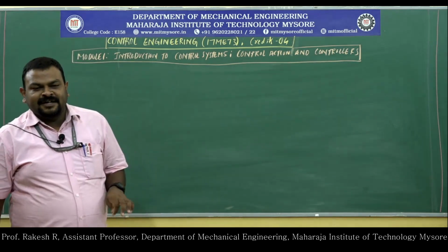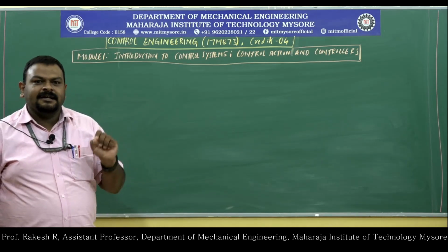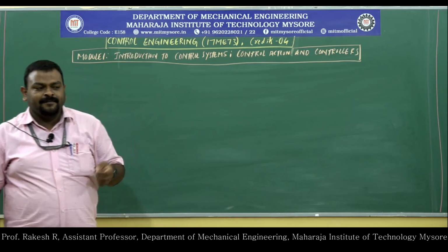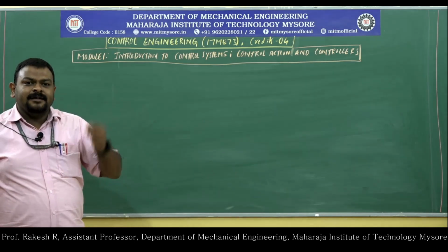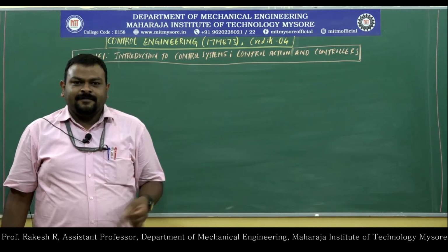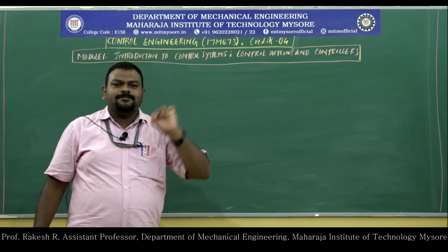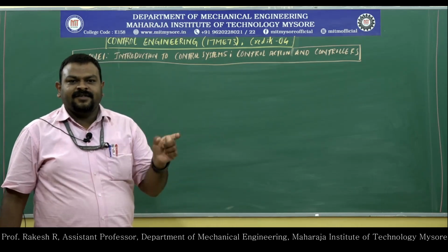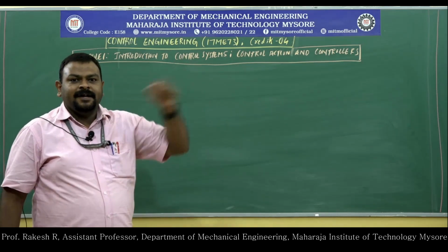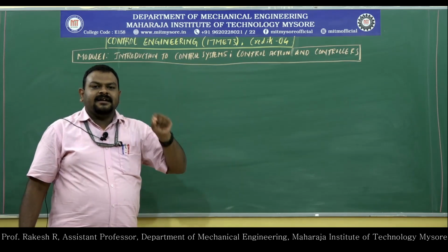If we take the integral controller, the response of the system will be slower because of the integral control action. There will be a divided by S term that increases the order and type of the system, because of which the system will tend to become unstable. That is the limitation of the integral controller. The derivative control system will directly respond to change of error. Because of that, it will take early corrective actions before the output of the system goes wrong. So, these are the limitations of proportional, integral and derivative controllers.